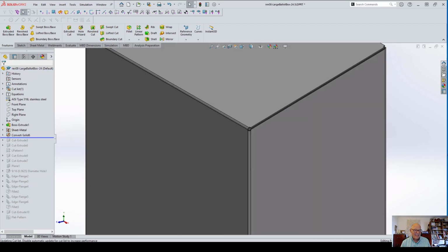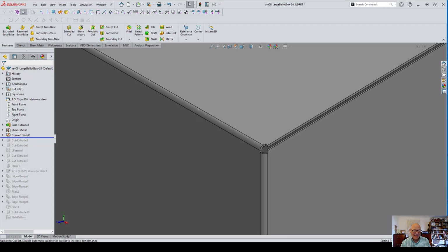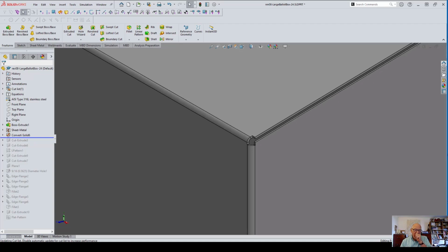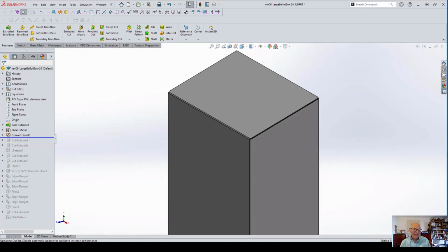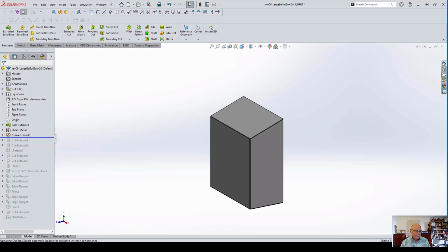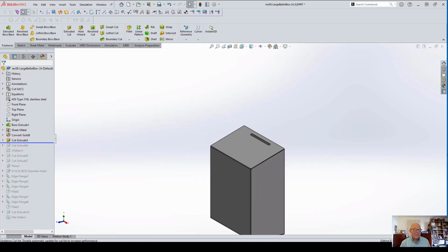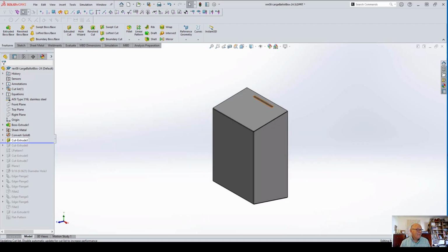And you notice now it's showing the radius for the bends, and it's also showing that little relief right there. The gap is because it's going to have a gap in order for the welding to take place. And then I said, all right, once that's done, we got to put a slot in it. The actual slot's actually narrower than that and back further, which is what I wanted. And they made it that way.